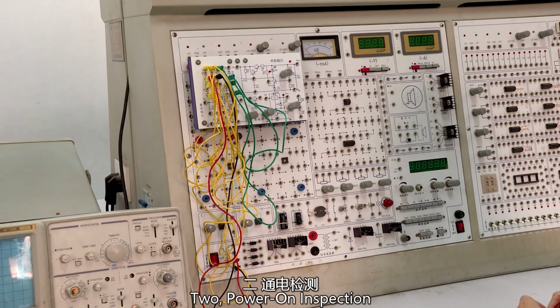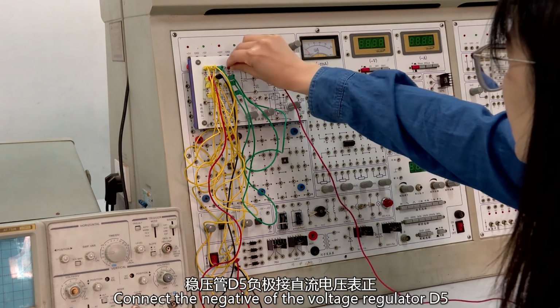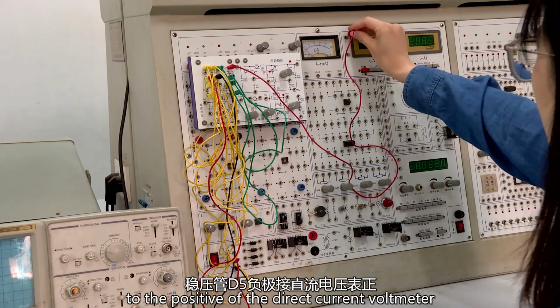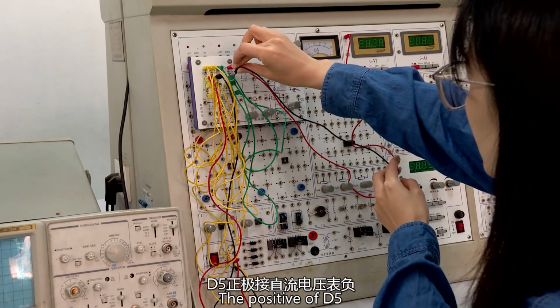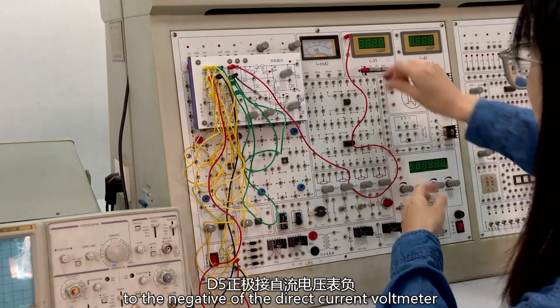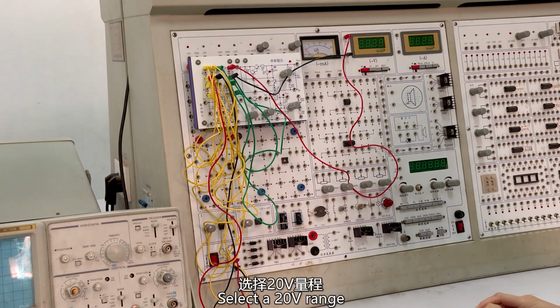2. Power-on inspection. After visual inspection, connect the negative of the voltage regulator D5 to the positive of the direct current voltmeter, the positive of D5 to the negative of the direct current voltmeter. Select a 20-volt range.